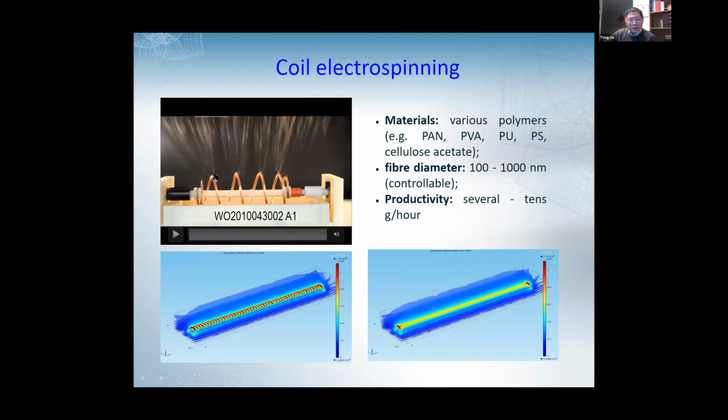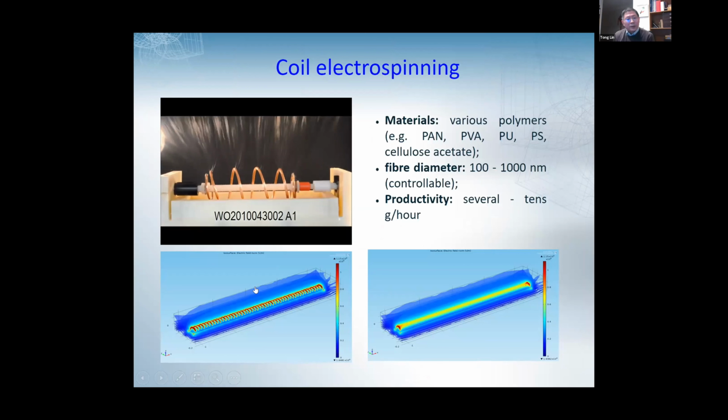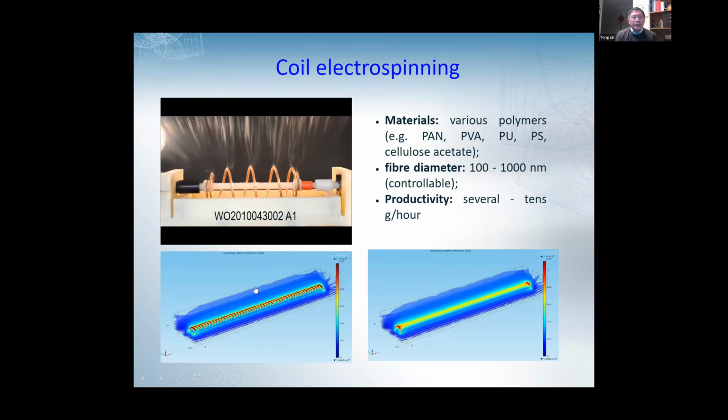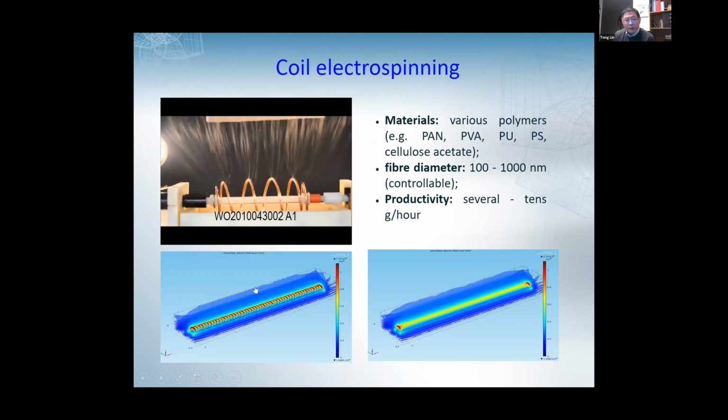We have a cylindrical coil, which is partially immersed into a liquid solution, the spinning material, so we can get nanofiber. We got the international patent on this in 2010, and I can give you a video to show it working. You can see all the coil surface is a generator area. It can produce nanofiber in a tunnel area on large scale. The benefit of the coil is the wire shape, left and right. This can improve the evenness of the fiber distribution.